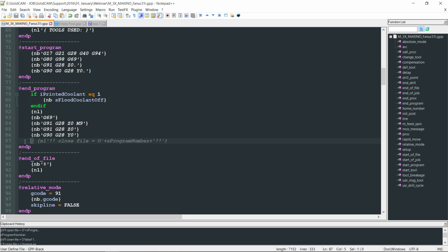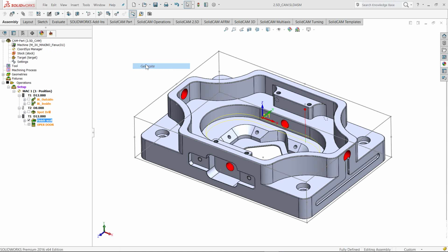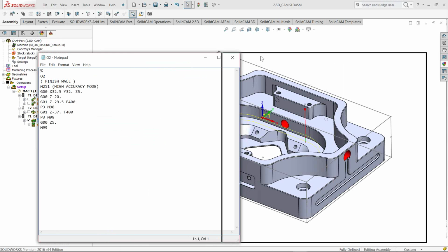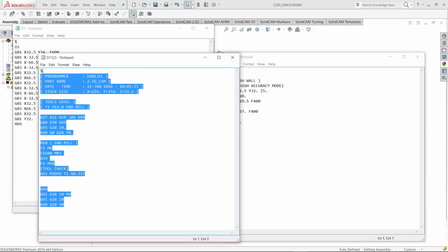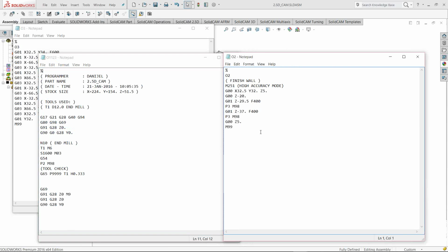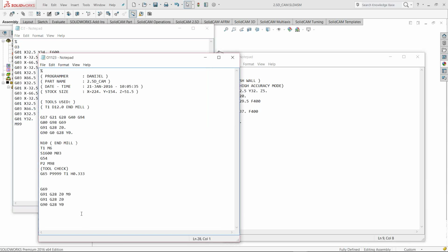So for now, let me just close it. And the closing of it is just putting the semicolon on the end, and the GPP file will not even execute it. Let's see what will bring that. I'll generate the Gcode, click OK, and wow, we have one file, third file, and another file. This is the main Gcode, which will call this one, and this one will call for another one. Pretty handsome, pretty tricky, but I guarantee that you will figure it out.